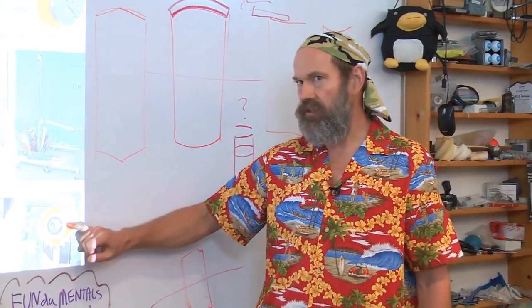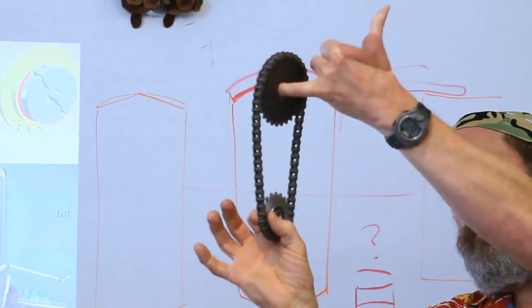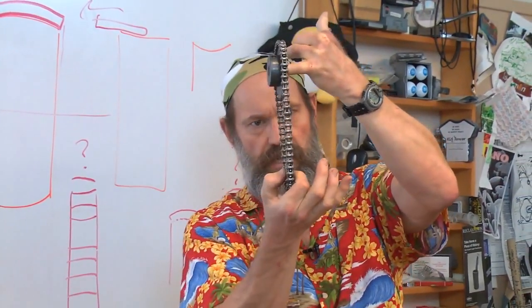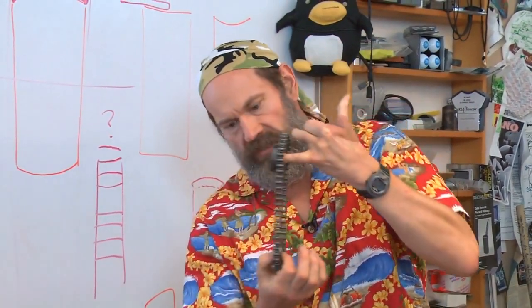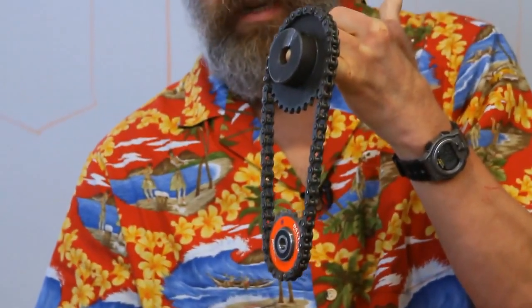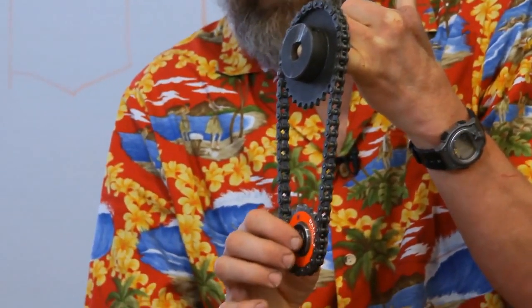Idlers, notice here, it's very, very thin. As a matter of fact, you'll see that the width of the bearing through the center of the sprocket is at most the diameter of the sprocket. And you say, well, that's not good for St. Venant's principle in terms of alignment. Well, that's kind of the purpose.